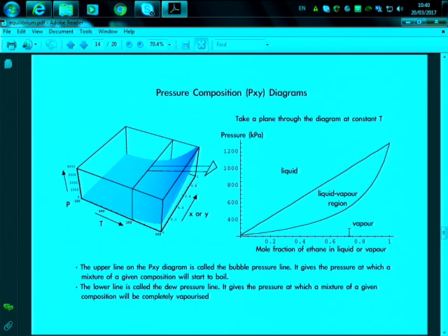Okay, so normally these types of pressure systems are useful for compressors and for pipelines, and there are systems where you will have a multi-phase flow. You are using equipment for a multi-phase flow, but you want to know how the multi-phase flow is changing, because the pressure will change and it will affect the binary mixture, and therefore you want to know that, and you can know it through here. So that's why we have these curves of pressure against the mole fraction of a binary mixture.